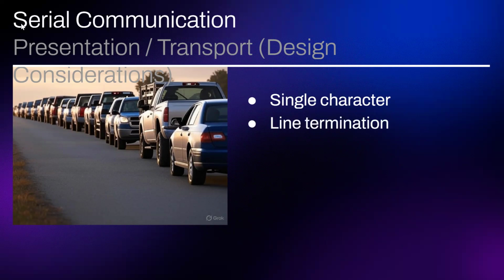You can send, every time you see a carriage return or a carriage return line feed, package up that line and send it off. Arduino probably uses that kind of mode, or maybe you can set it to single character mode as well. It's not great either. I've seen a lot of errors happen using that kind of a protocol to send your data.